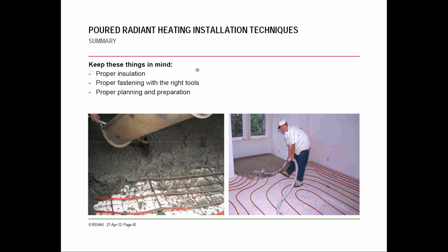So just a quick wrap up here of the over pour especially, but applies to slab on grade as well. Keep in mind insulation and your work surface underneath. Depending on what fastener you decide to use, which, as I alluded to, really depends on what your sub base is, and then how big the area is, how much and what tools you have available to you. And then just planning and coordinating with the other trades is so key here.